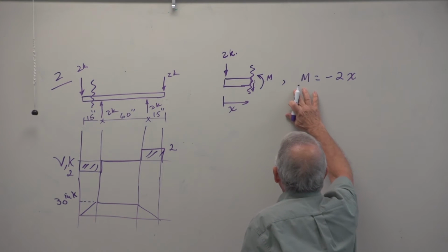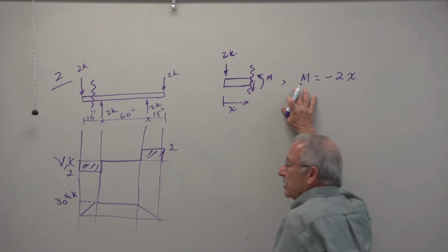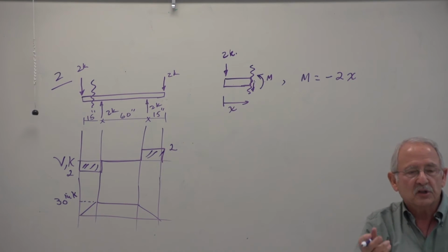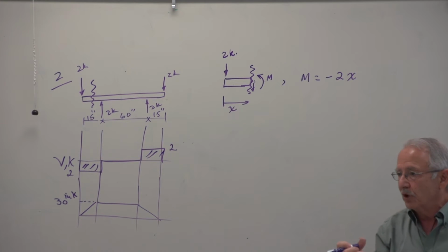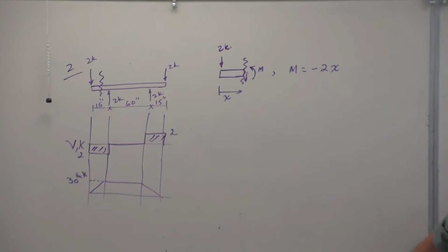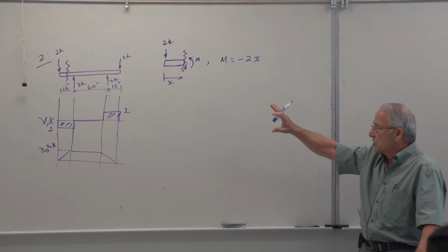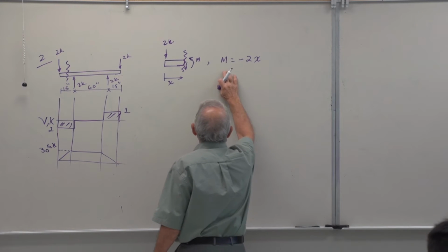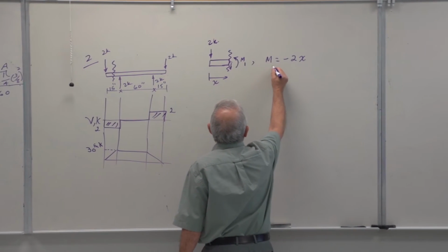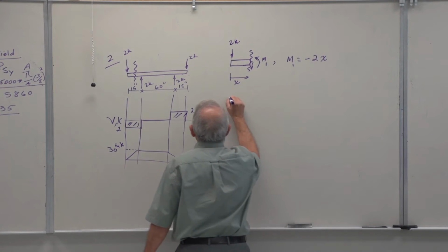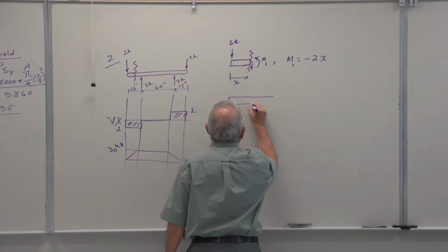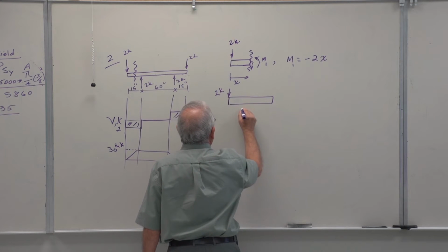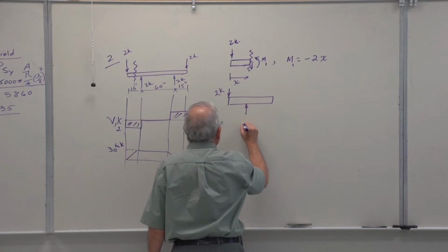Once you find the equation for the moment, take the partial with respect to whatever it is right then and there if you're doing a Castigliano's problem for deflections. In this case, we're just finding U. But if we were, I would take the partial right here. So this is the first part. I'll call it M1. For M2, I'll have this configuration.